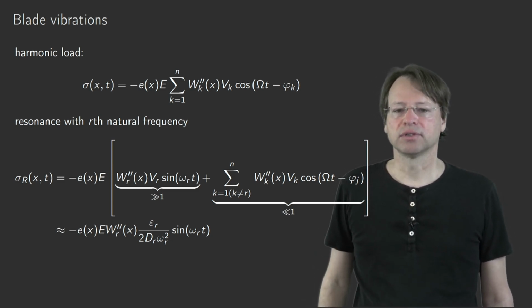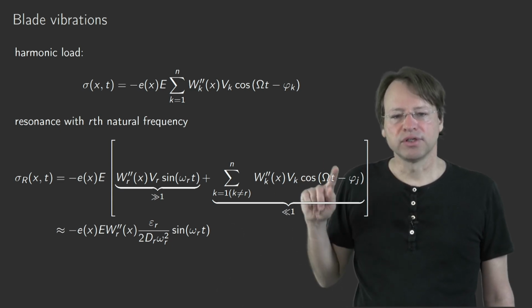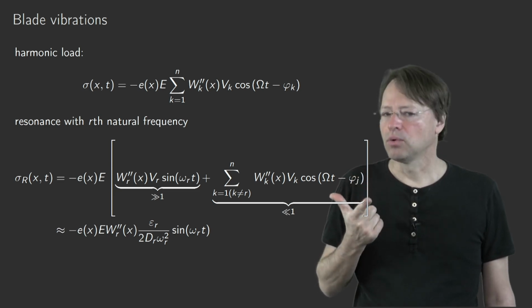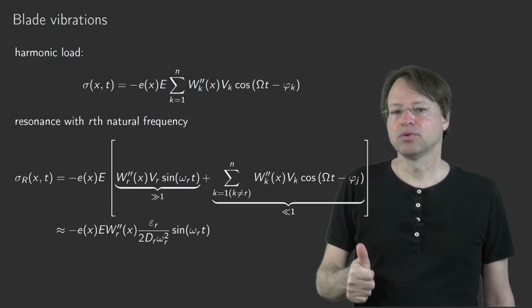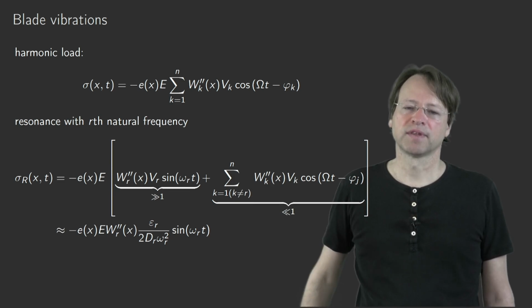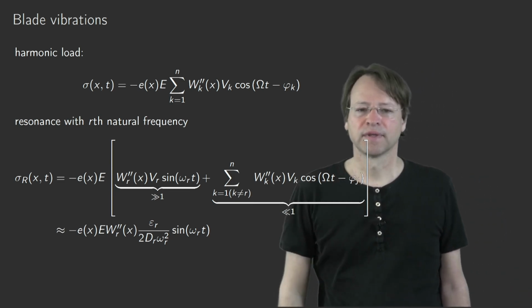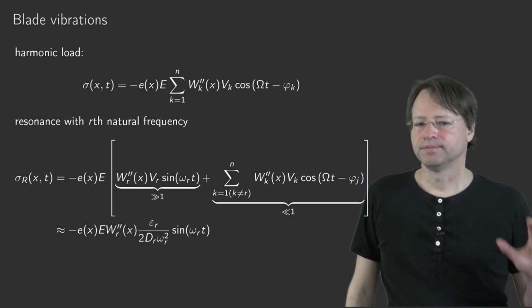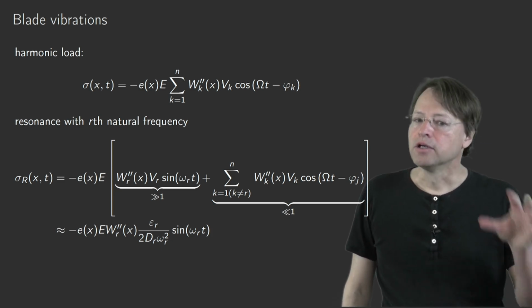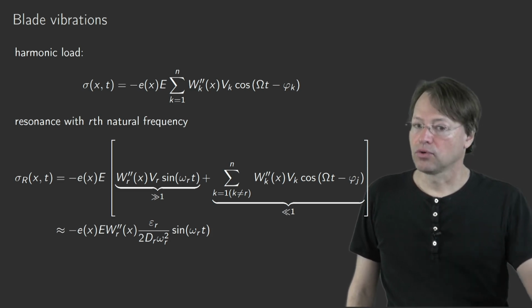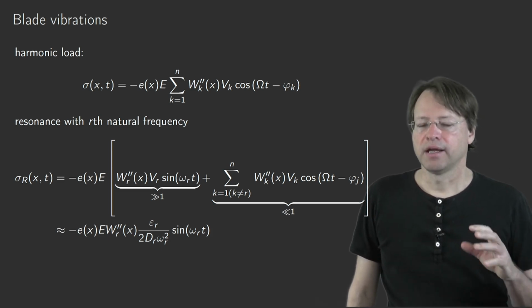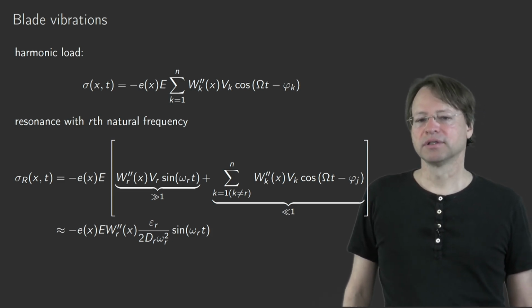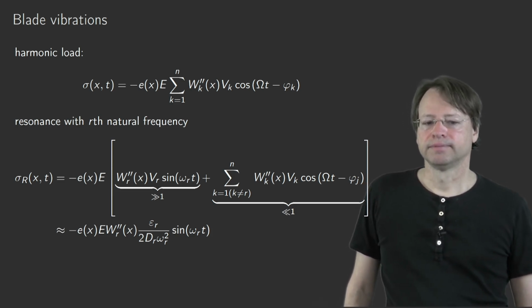So basically, all these computations in that Galerkin scheme have to be done only for 2 modes, the resonance mode and the first mode. And that's it. So this really reduces the computational effort to the determination of the modes, and the rest is a simple post-processing step, I would call it.